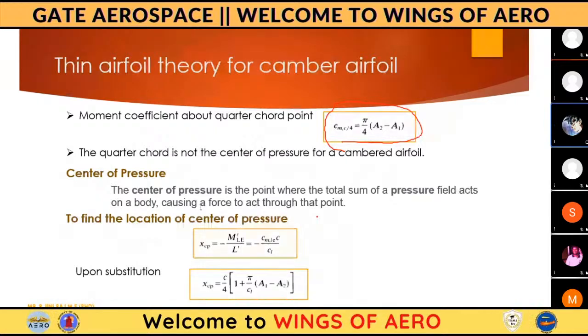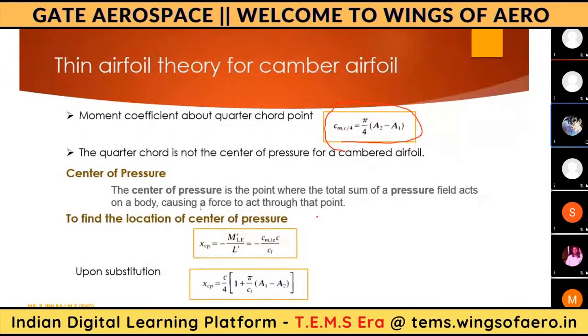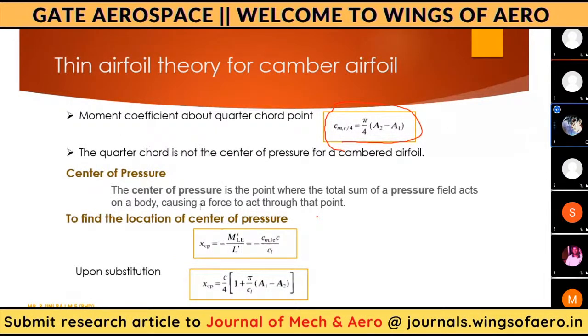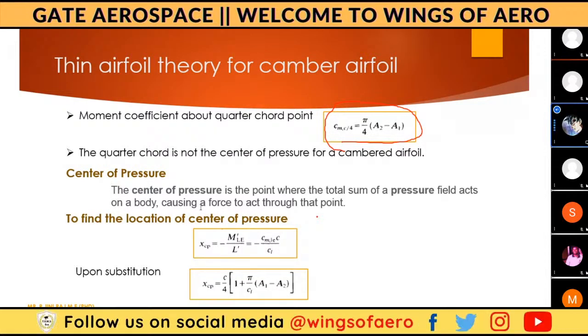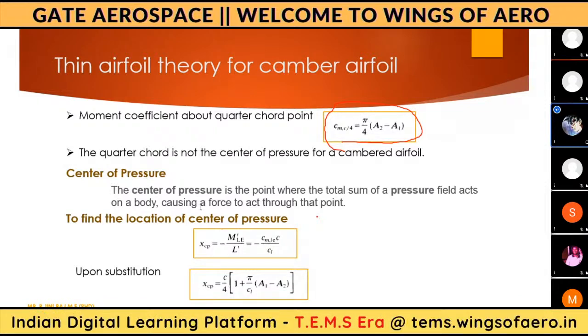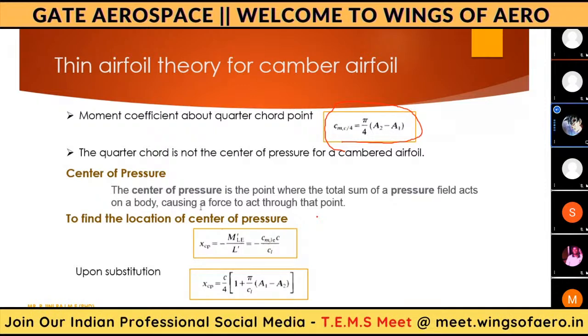Actually, center of pressure, you explained in the previous class, is a particular point on the airfoil where the lift actually acts. Yes, the forces act at that particular point. I'm repeating this once again because sometimes they will ask the concepts. In the 2018 GATE exam there was a question from this cambered aerofoil, which I asked some moments before. The question was: the pitching moment of a positively cambered NACA aerofoil about its leading edge at zero lift angle of attack is.